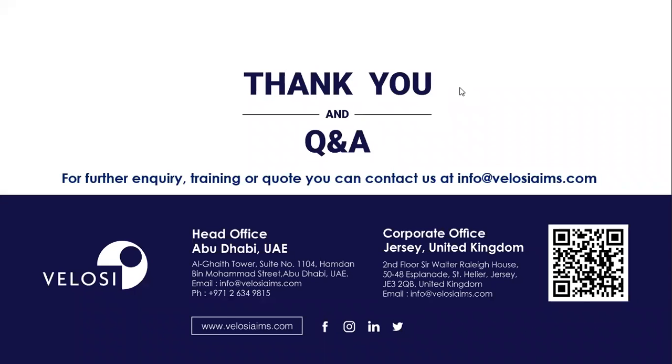Yes, there's no certification required for the technicians and engineers working in the plant. Yes, for execution of SIL classification, SIL verification exercises or studies, it's better the persons are trained or certified, whatever is the company preference. But basic knowledge is required about IEC 61511, 61508, and ISA standards, so the information can be used in a proper way.